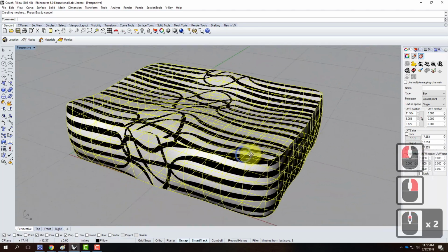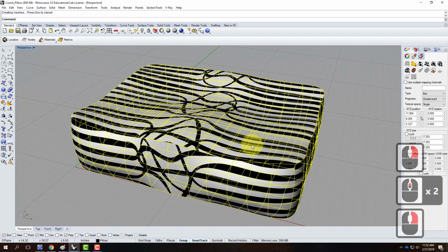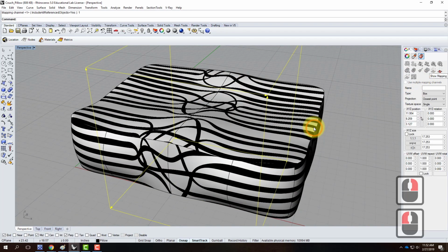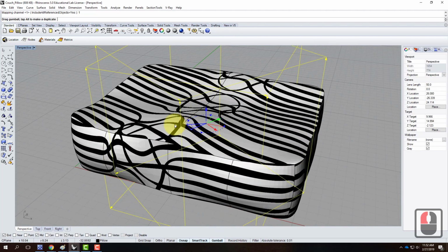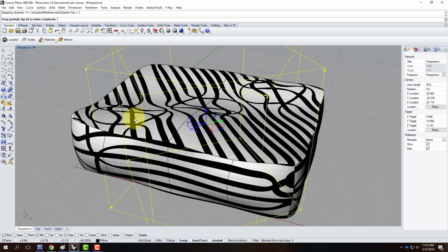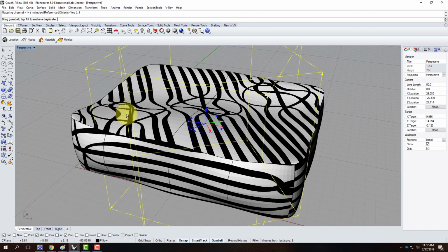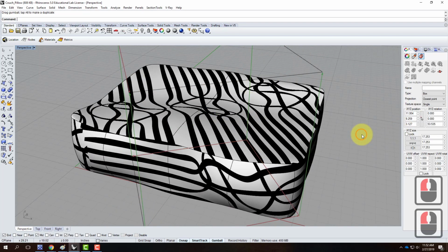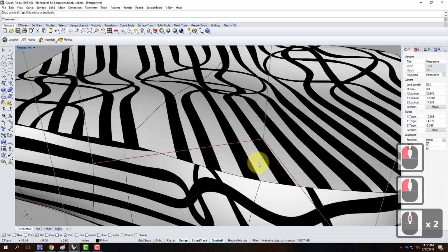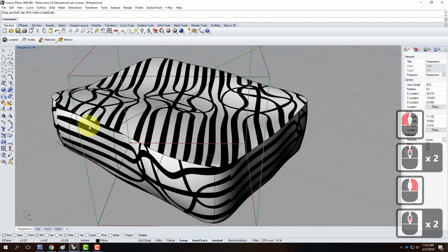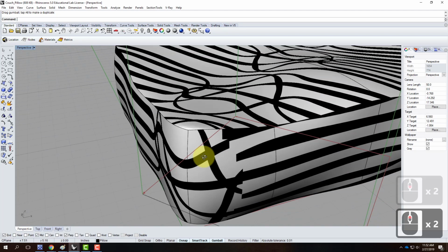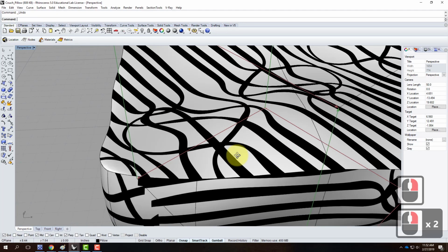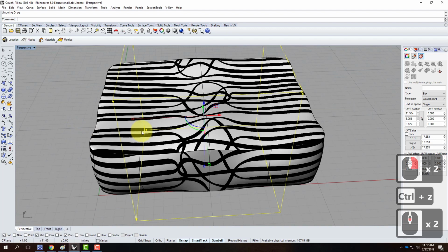Now in this scenario, I might spend some time adjusting the texture map. So I might show the mapping and turn on the gumball and decide how I wanted the pattern applied. So maybe I wanted the pattern applied that way. Point is, take your time. But in this scenario, no matter how I do it, there's always going to be issues at the seams. Right? There's no real good way around it. I also created a really nasty seam right there by rotating it. So maybe I'd go back and keep it in that scenario, like that.